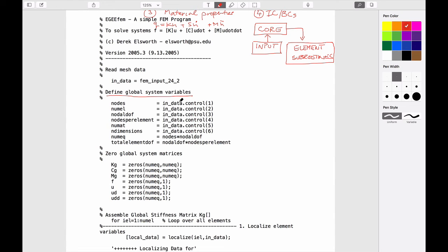what are the big picture components that describe our system. How many nodes do we have? How many elements do we have? How many degrees of freedom do we have? In the stuff that we do here, it's not so important, but in most commercial scale finite element codes, if you know how many elements, how many nodes, and how many degrees of freedom you have, in our head finite elements, 1 degree of freedom per node, then you can calculate exactly what the storage is that you need.